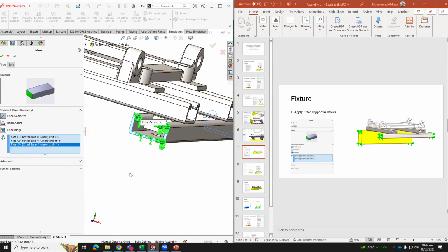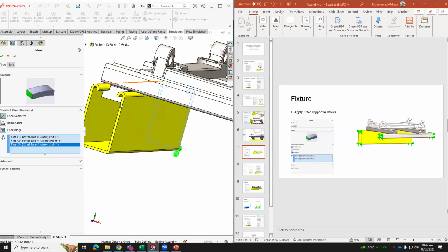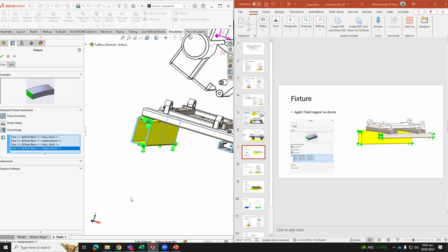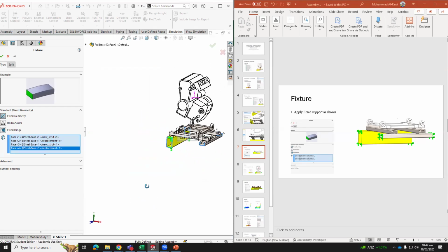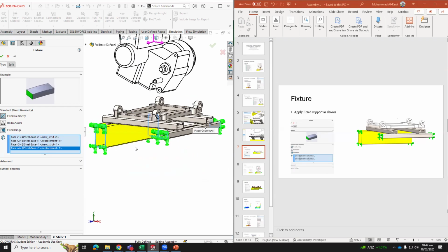Okay, so that is a face. And then I come here, it must be the face, not the edge. And then I bring the mouse here, face 3. So those faces, I need to select them one by one. I'll leave it here till I check with you guys. And every time, check your selection. If I selected an edge by mistake, delete it and bring the face. Perfect, perfect. Check the face, and if you have an edge selected, delete that edge.